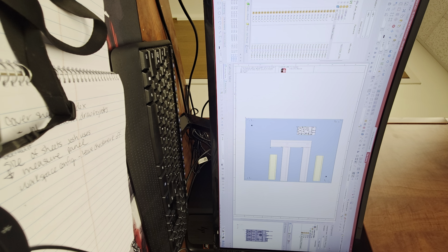Right. But if you are designing this, obviously you know what you're committing and why you're editing it, so you would just come to this component, either from the model perspective, by putting your mouse on it, or by selecting it on a device level, one level up, or even from a folder or library level. You have the option to right click and say update in project, or update all components in project. So when you select update in project, not the attributes, but the whole component, one level up, update in project,